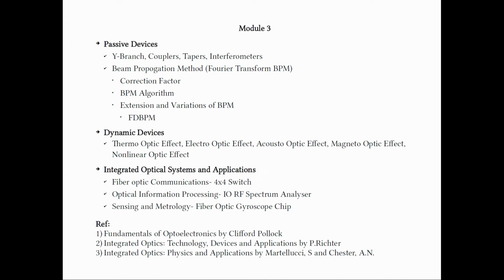Strictly speaking, we cannot talk about the modes of these devices, but we have taken an approach where you can think of normal modes. At any given cross section, we can assume the device to be uniformly extended and consider the mode of that particular straight waveguide and use that mode to analyze these properties. In particular, we have mentioned that we can divide the device along the propagation direction into several small segments, and in each segment we can find out the local normal mode and then study the ray propagation in each of these segments.